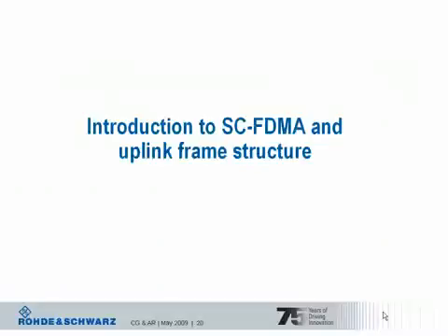This is already challenging in the downlink, where we have no trouble providing power or space for the design. On the terminal side, this is nearly an overkill. The goal for 3GPP was to select another transmission technique for the uplink that keeps the advantages of OFDM, which is multi-carrier transmission and therefore an efficient use of the available bandwidth, and combines this with the advantage of a single carrier transmission, which is, compared to multi-carrier, the lower peak to average power ratio. As the name already emphasizes, this is achieved with single carrier FDMA.